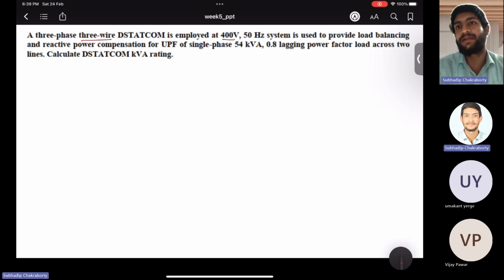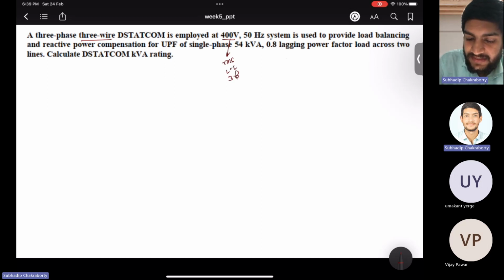I don't mention that, but generally in power systems, when you hear of 3-phase systems, they are star connected. And whatever voltage is given, this voltage is the RMS line to line voltage. And this is star, you have to assume like that.